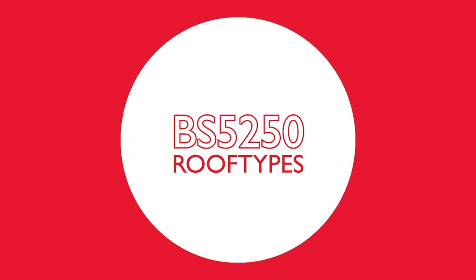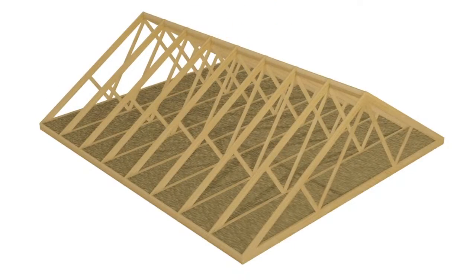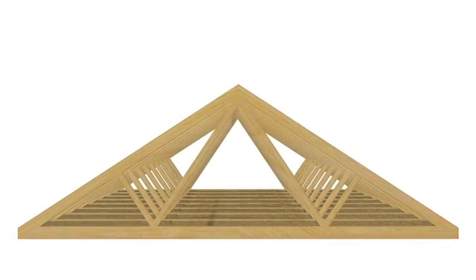BS5250 defines 4 classes of pitched roof constructions, with a pitched roof being a roof over 10 degrees of pitch but less than 70 degrees. Cold pitched roofs: in this type of roof, the insulation is placed horizontally across the ceiling ties, with the loft space and the structure of the roof being outwith the building's heated envelope, hence cold. This type of roof typically uses fibrous quilt insulation, which is both air and vapour permeable.